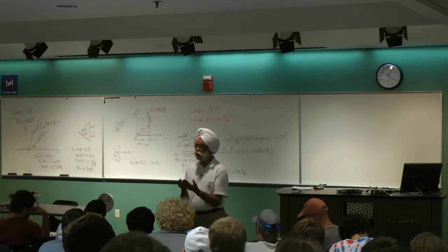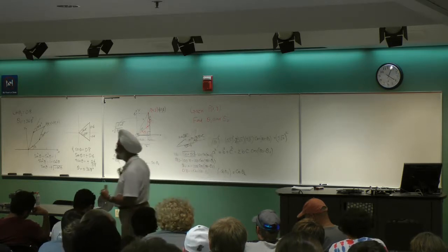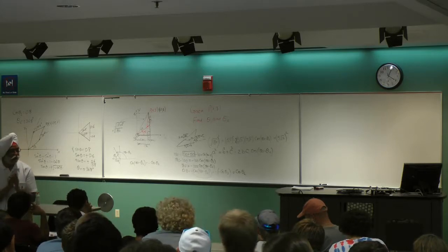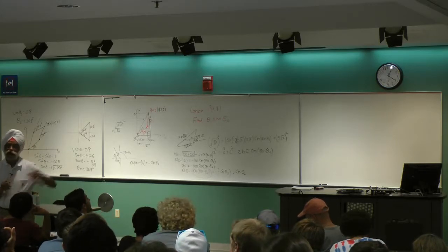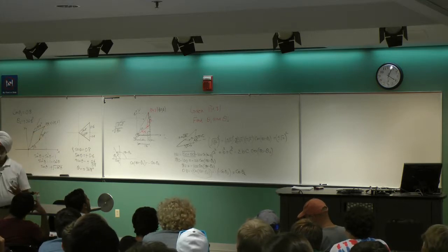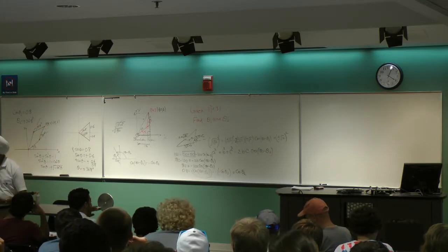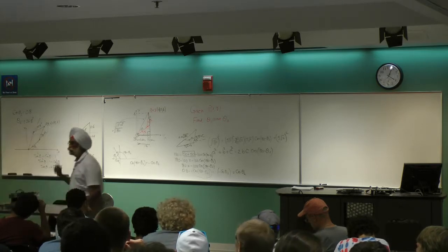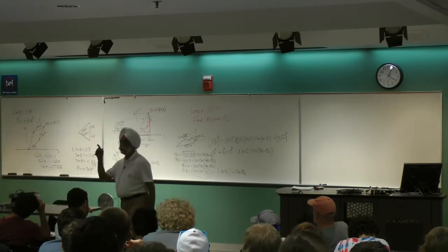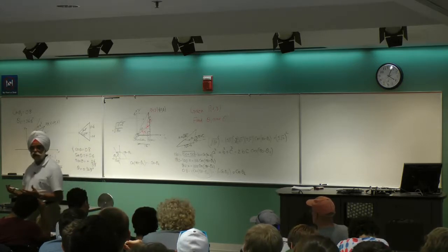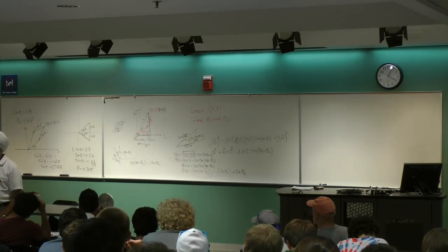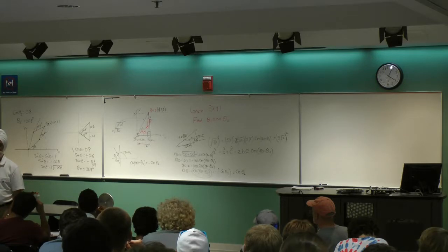It's okay here because you know it's elbow up, so you know theta 2 had better be positive in this case. If I had drawn it the other way around, you would know it's a negative angle for theta 2, and you would take the negative. But if you are finding all solutions, you know cosine of theta is 0.8. You find sine theta, which will be plus or minus 0.6, and find the angle using the tangent. Is that clear? It will come in very handy later on.